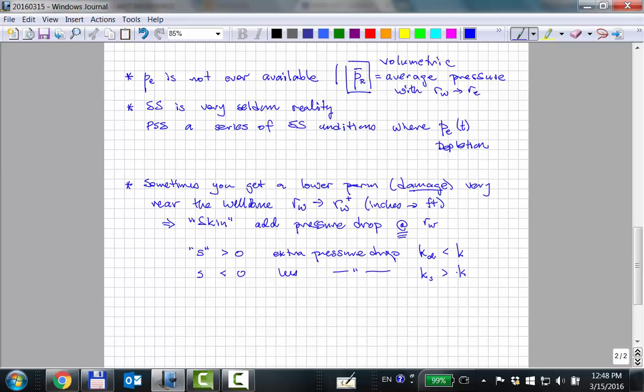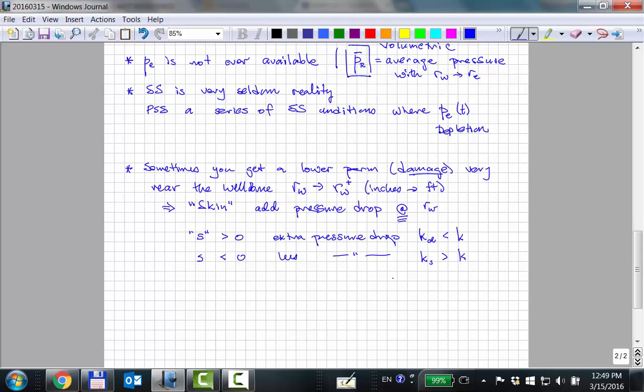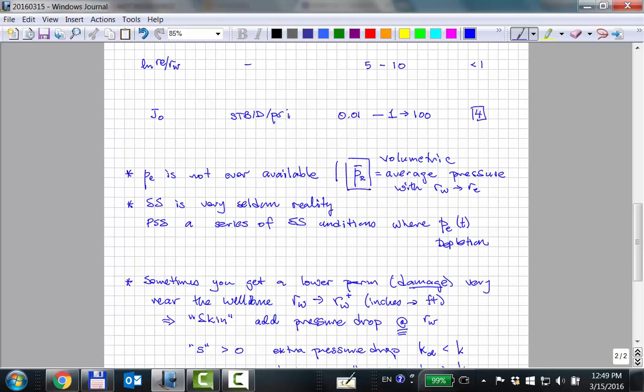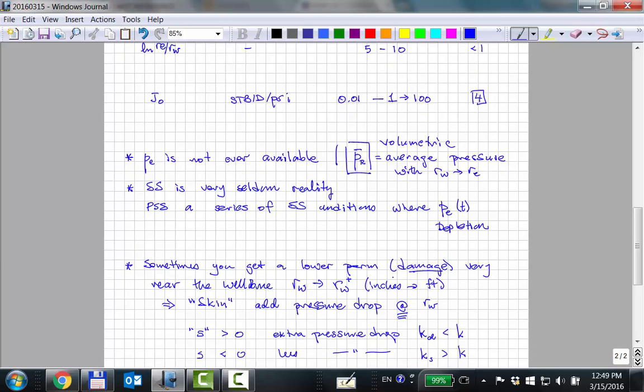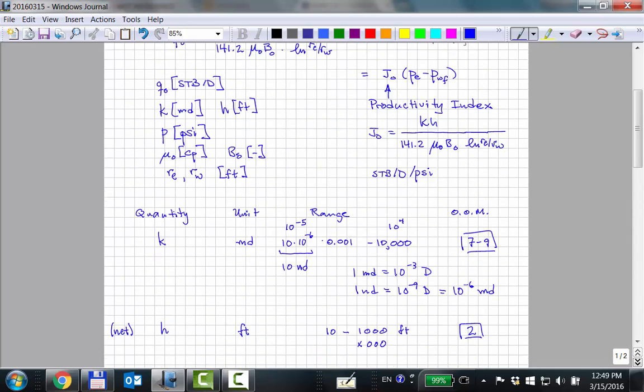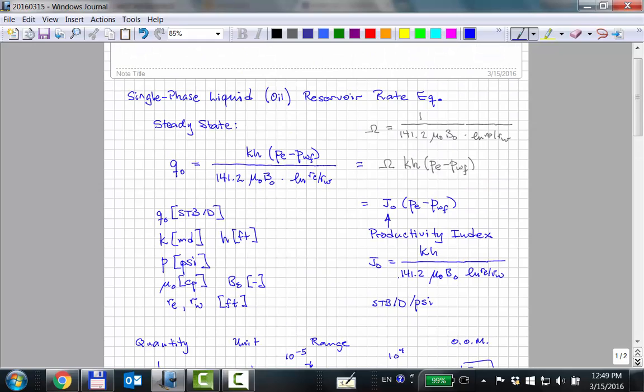The permeability of this is around 1 to 5 millidarcies in the Ekofisk field. In the worst case, 0.1 millidarcy, in the best case, 5 millidarcy. That's the range. Very narrow pore size distribution. But then they can stimulate it and get a bit higher permeability. So you can get a negative skin by increasing its permeability. This is not in the equation up here, but I'm going to add it. I'm preparing you for a new version, a more realistic version of this equation.